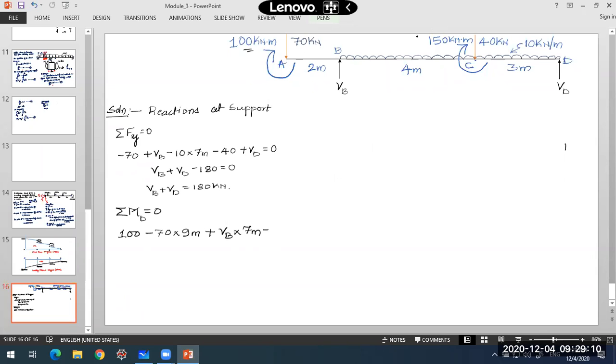So it will be having anti-clockwise. It is a downward force, and about point D, it will produce an anti-clockwise moment over here. Okay, so minus 10 into, it is present for a length of 7 meters, 10 into 7 into 7 by 2. Okay, so this is the moment due to this UDL, right? And there is one more couple at C that we are coming across. It is a clockwise couple. So plus 150 kilonewton meter, this clockwise couple I have added to my moments.